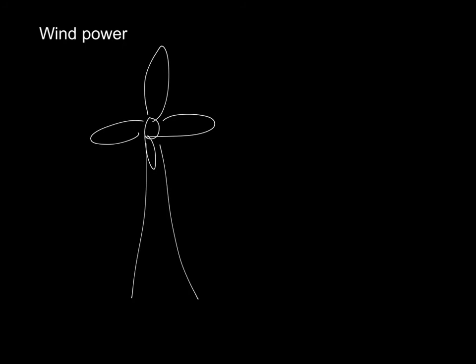So what are the subtleties of this thing? Well, the first thing is that these things are optimized for certain wind speeds, the average wind speed. So let's say the typical wind speeds are 6 to 14 meters per second. Now, in practice, sometimes you have much stronger winds that can damage your equipment. So you need to design these things so that they're not going to break when there's much stronger wind.